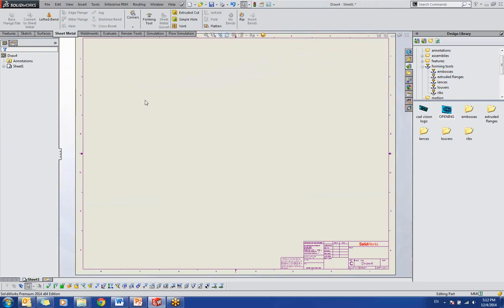If I am using sheet metal, inside the selections, front view, right view, side view, at the right side of the interface here, it pops up another new view called flattened view. This is the most important for the sheet metal industry. What do they make in the drawings? They do not make the front view, they do not make the side views. What they make is the drawings of the flattened view. Let my computer load it first.